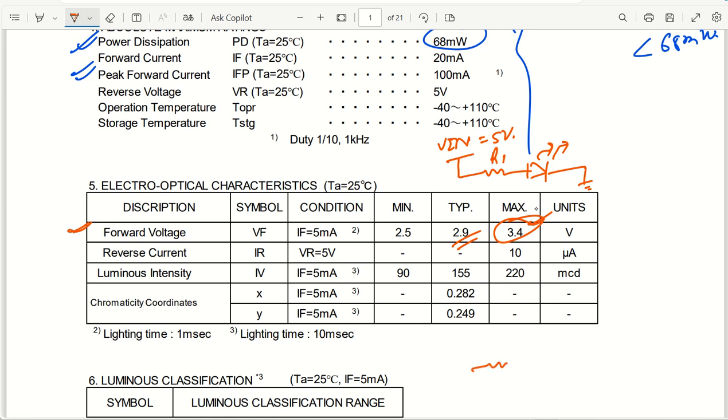Let us say I want to utilize my microcontroller as the sink. Okay, in that case this will be going to my MCU pin, which will be 5 volt tolerant. And this is my LED, and this is the source, right, V in.